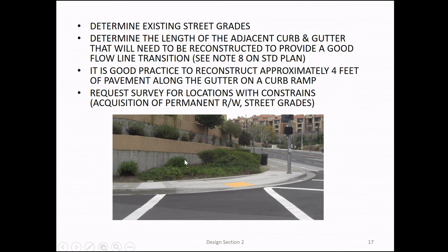So that 5%, that picture you had before, that's going to apply to your cross gutter too. The 5% in front of the flow line, if there's a cross gutter, it's going to be the same. Well, there's no agency that tells us how long that 5% should be, so we think it's just 2 feet. Even Caltrans says that no one says how wide that should be, or how long. So if the gutter is 5%, that's all we need.